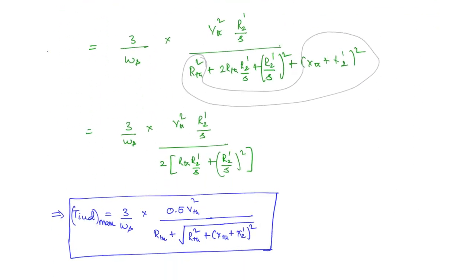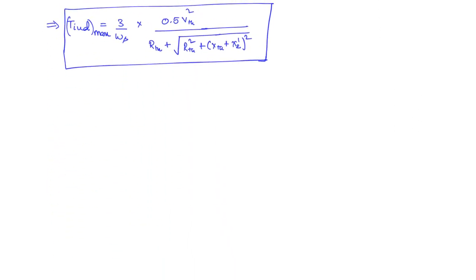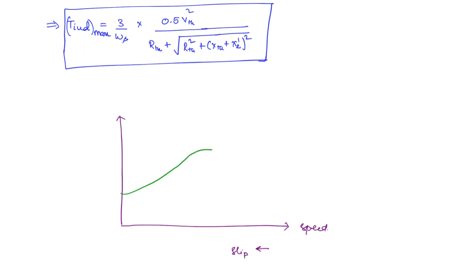Okay. So if you see the characteristics, it will become more clear to you. Let us say this is the torque axis and this is the speed axis. Slip is increasing in this direction. Now at one particular slip, let us say this is the characteristic. Let us say this is R2 dash and this is where S max is, the slip at maximum torque. Now when you increase the resistance, what will happen? The S max is going to increase. So that means the peak will move in this direction.